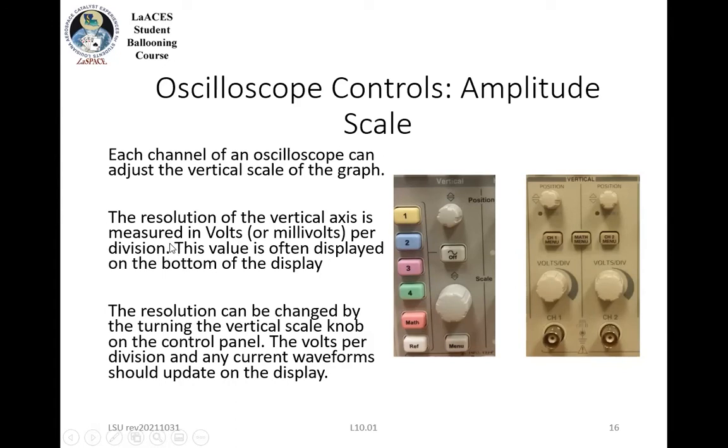So yep, the vertical axis is usually going to be volts. And for these, you can independently adjust the position and scale of each one. In particular, if I have 2 signals that I'm trying to look at the same time, I may want to shift them off of each other so they're not right on top of each other so I can see each complete signal. Or I may want to make them match so that their zeros line up with each other so I can see how they compare with each other.